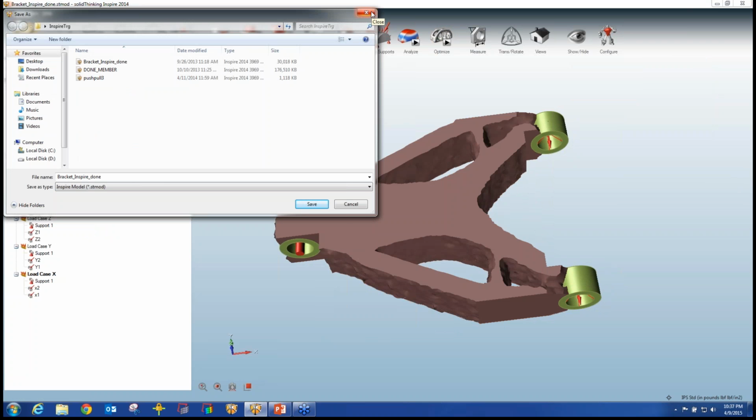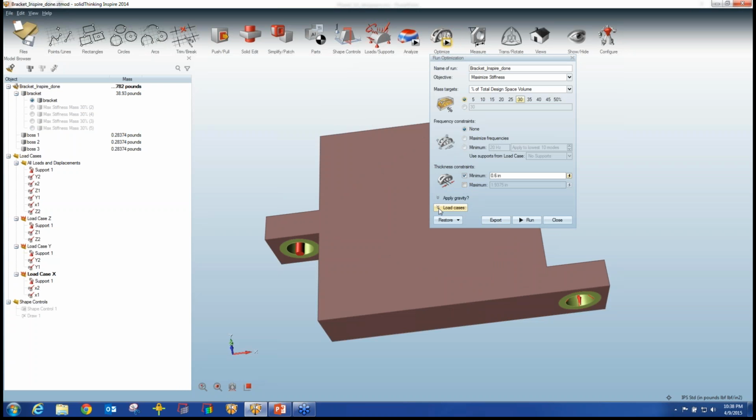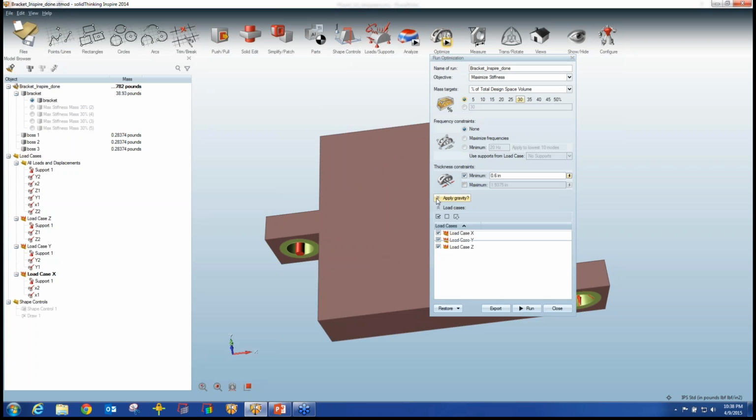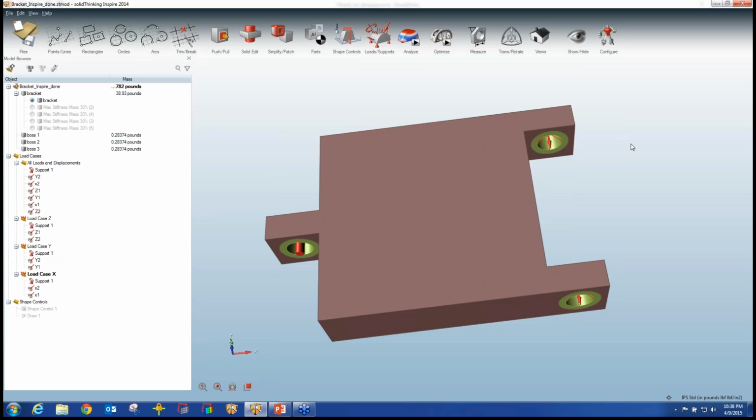Okay, great. The second question is, can the meshing that was generated to optimize this design be preserved and opened in HyperMesh? Yes, you can. There's more than one way to do it, but the main way would be to export. Once you've got everything set up, you just click on export, and it exports a .fem file into your run directory, which you can then import into HyperMesh and immediately solve in OptiStruct, because it's going to have the material definition, the loads, everything.